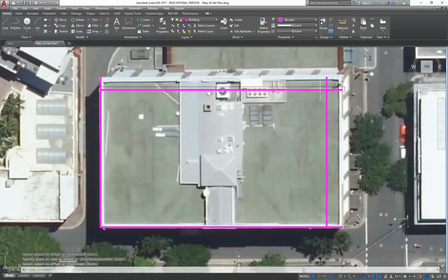And so you can see how far off the satellite really is. So I'm going to fillet those to make a rectangle. Now I'm clicking on the button each time just so that you can see what I'm doing, but if you press enter in between each fillet command, that will repeat it and save you clicking on the button every time.